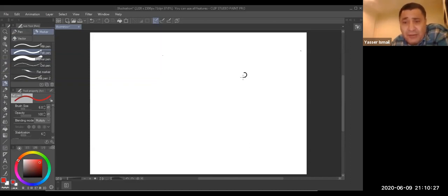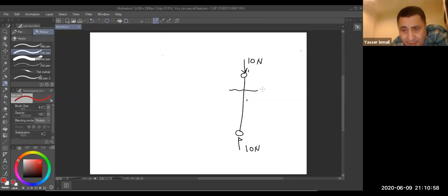You have a joint, and you have a member and joint. This joint has force in this direction, 10. And for sure, 100% to make this stable and in equilibrium, this should be 10. 10 Newton, 10 Newton. 10 Newton. Okay. Cut in this, cut here, section 1, and cut here, section 2.